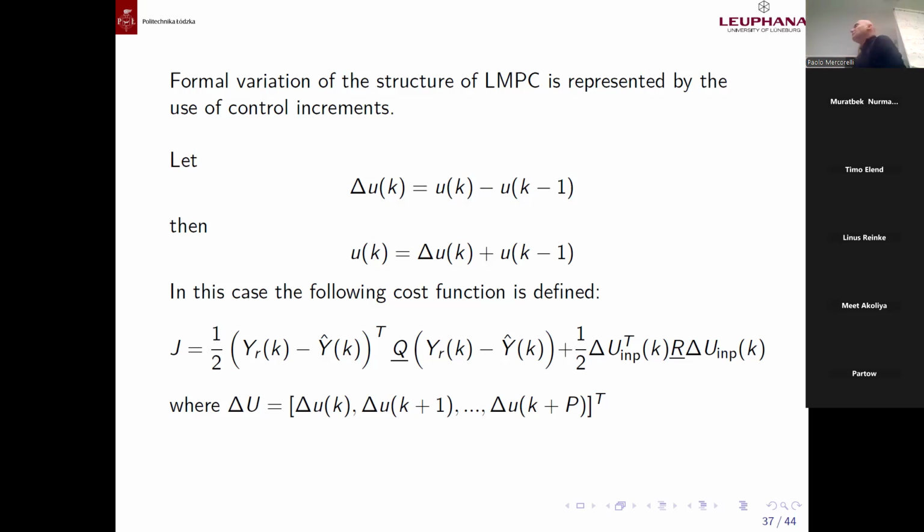And in some cases, we can consider it's easy to be tuned. What is the meaning of to be tuned? To calculate the value of Q and R. The reason is, we will see now, the solution depends also directly on UK minus 1. This means it seems that the solution has more inertia, let me say, because it depends on the past. Therefore, somehow it is easy to be tuned. Easy to be tuned means also to consider Q and R which stabilize the controller. About the stability, I didn't tell you anything. It's not included in this analysis.